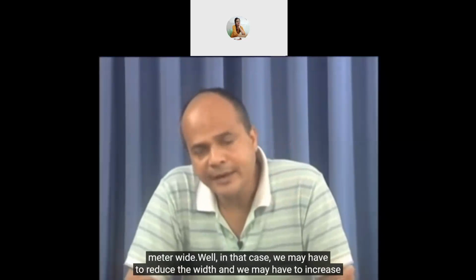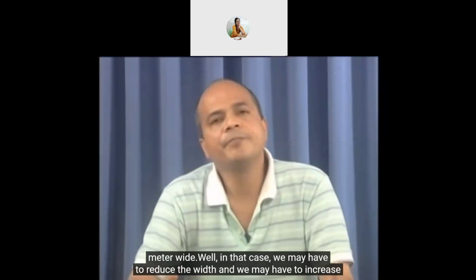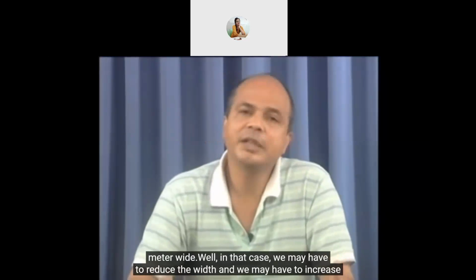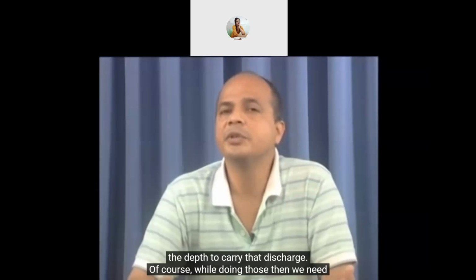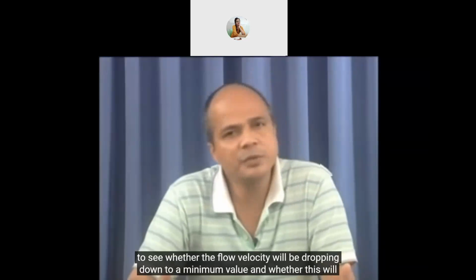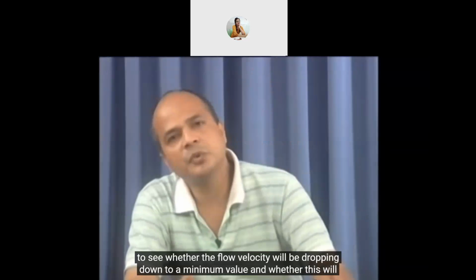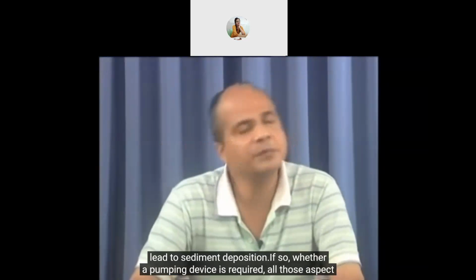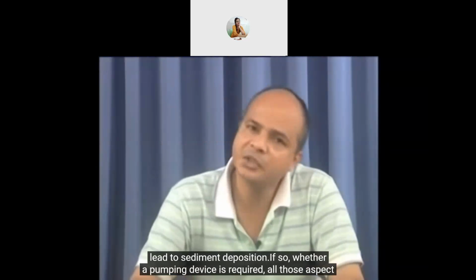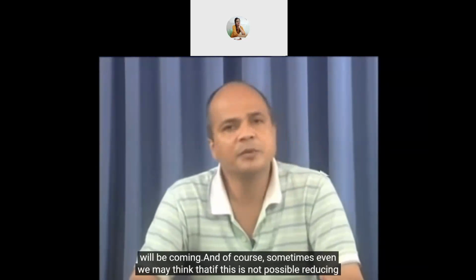Well, in that case, we may have to reduce the width and increase the depth to carry that discharge. Of course, while doing those, we need to see whether the flow velocity will be dropping down to a minimum value and whether this will lead to sediment deposition. If so, whether a pumping device is required. All those aspects will be coming.